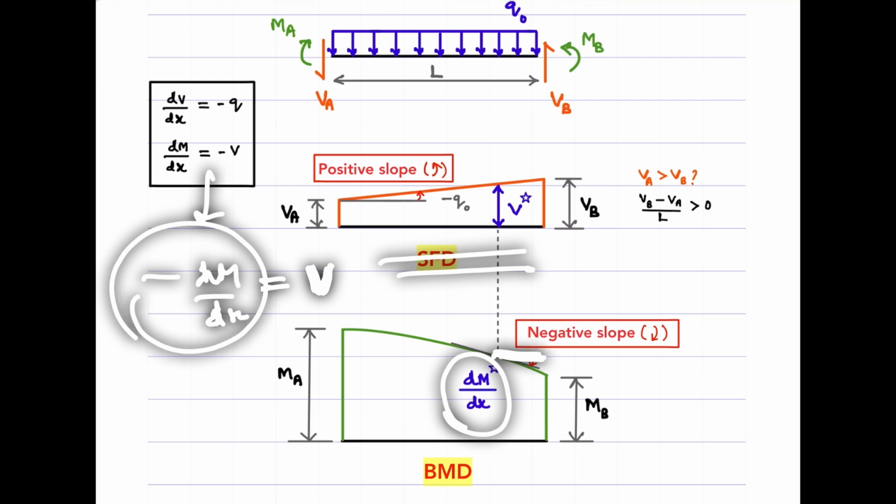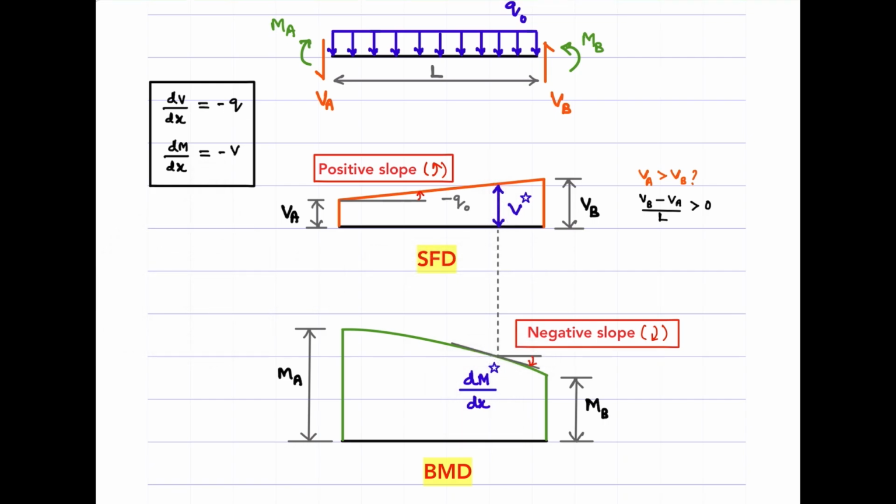Okay, that should give me the value of the ordinate at the same location in the shear force diagram. That's what is happening, right? So at different locations, I can draw that and find the slope. We see that the slope is constantly increasing and it's a negative slope. So I need to add a negative sign to that, minus dV/dx, which will give you a constantly increasing ordinate in the shear force diagram.